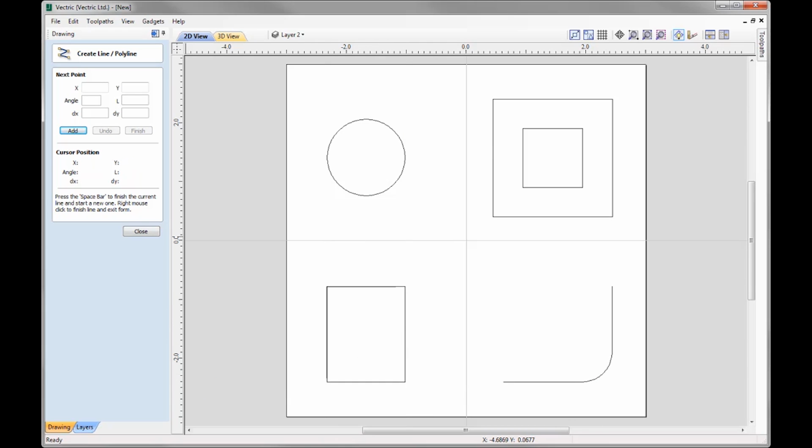So we've looked at the object bounds, we've looked at horizontal and vertical lines and angled lines. Now Smart Cursor can also pick up tangent lines. So let's wake up this circle here, and if I just move my mouse along, you can see that the software has found a tangent line, and I can click and then I can just follow along that line, click that in place.